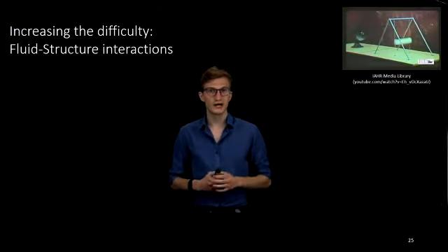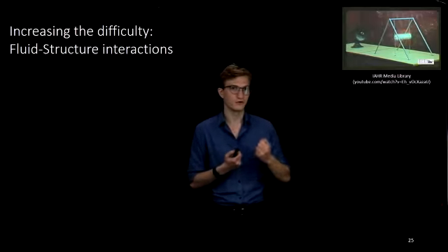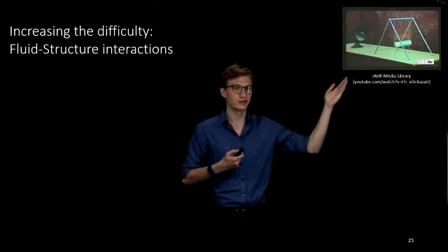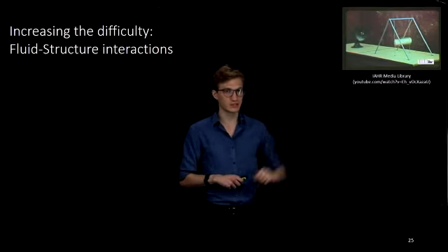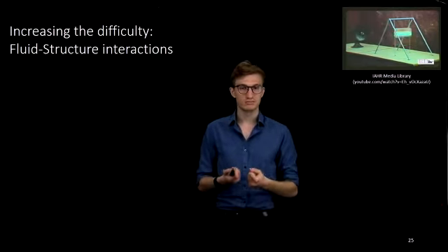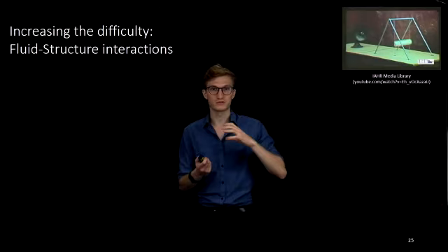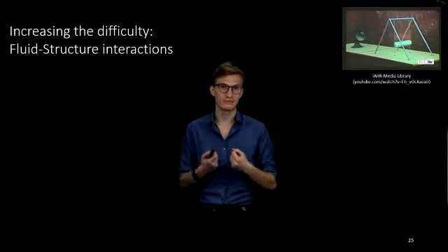Finally, we wanted to look at the effect of fluid-structure interactions. We look at the test case of a cylinder on springs, which is excited by the shedding of the vortices, as you can see in that animation. It's a test case that is well known in classical numerical simulation methods because the fluid domain moves. And when the fluid domain moves, you have to adapt your mesh or perform immersed boundary methods.